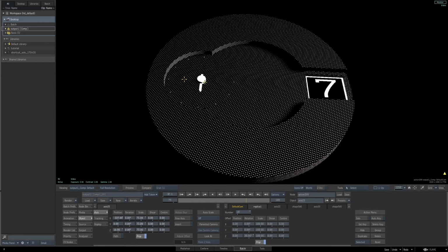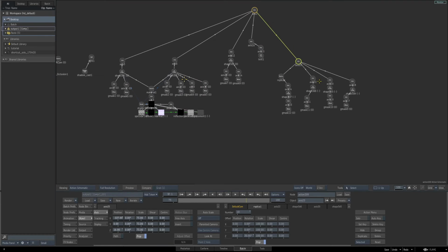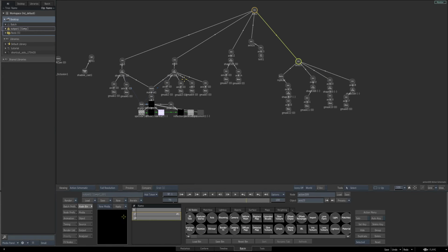Now I'm happy with the indicator and the dial where it's located, but we want to have further control over this, especially the dial. That geometry, the dial, is made up of these three pieces of geometry we have here on the right-hand side, and drag another axis out into the schematic. And then while holding the Shift key, I will connect each one of those axes, the top axis for those, and now I've created a master axis for all three of them.